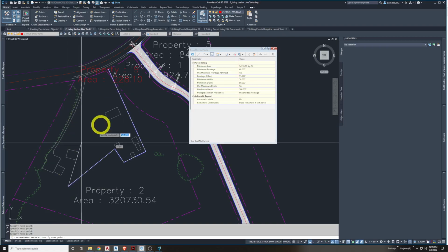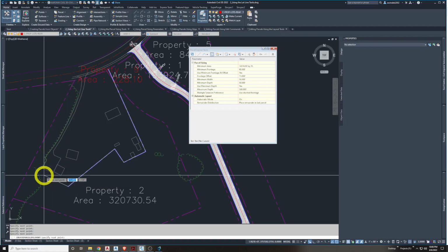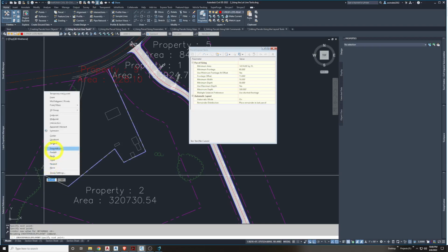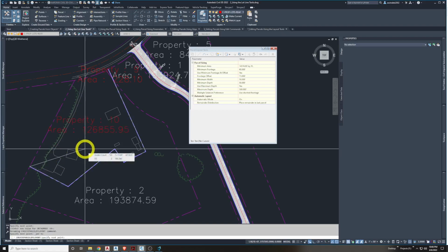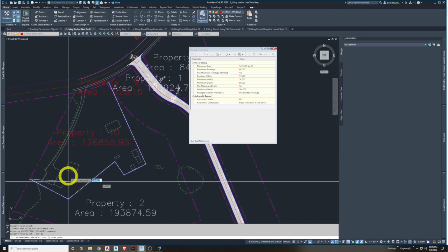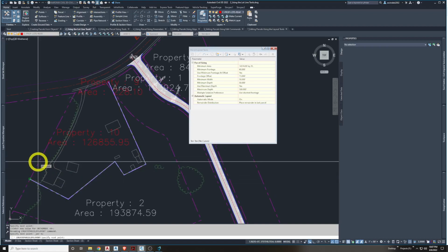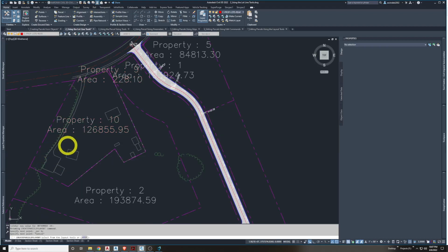We're making this existing parcel its own little cutout. Let's hold shift and right click this time, same as control, and then hit right click. We'll do perpendicular to there. And we just made our last selected point here to make this parcel. Let's hit escape twice to escape the command.